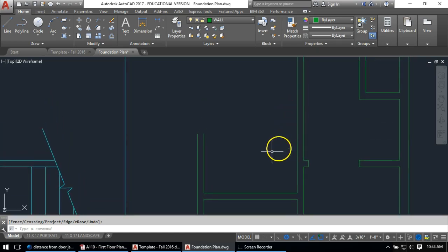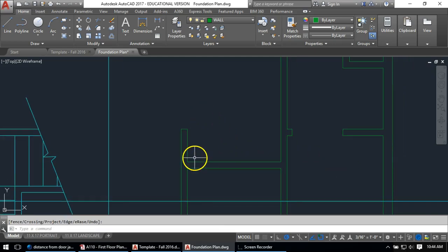And then the top of this wall is actually ending even with this line there. So I'll draw a guideline over and trim away what I don't need, just like that. And there is a wall in here, which is 3'8 3/4" over from the center point of this wall.